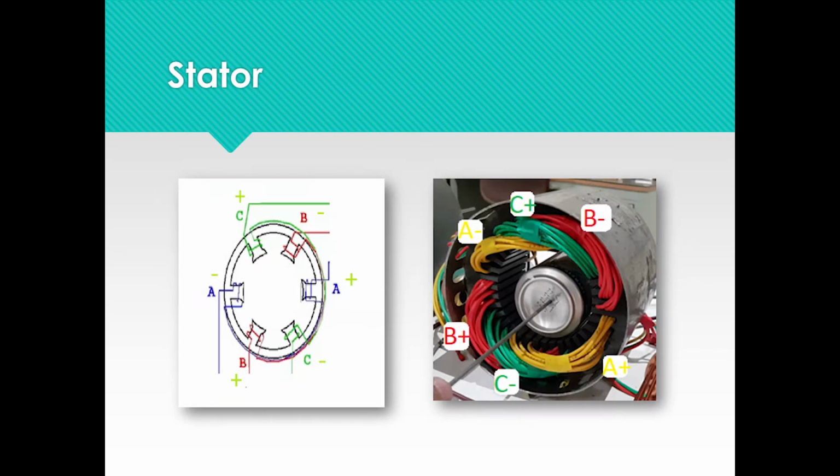Like other machines, induction machines consist of two general parts, stator and rotor. First we are going to talk about stator. There are three coils in the stator that are connected to the three-phase voltage, which produces magnetic field which induces a voltage in the rotor due to Faraday's law. Each pair of coils have a 120-degree mechanical angle difference as shown in the picture.